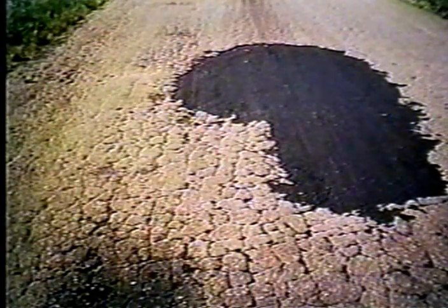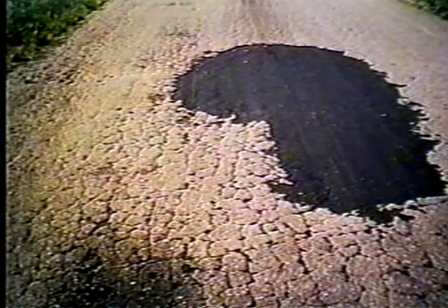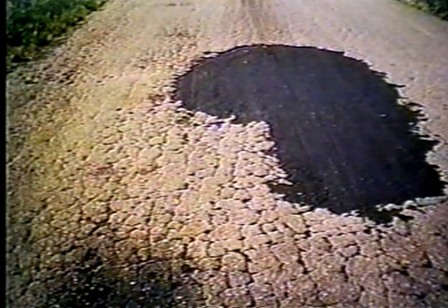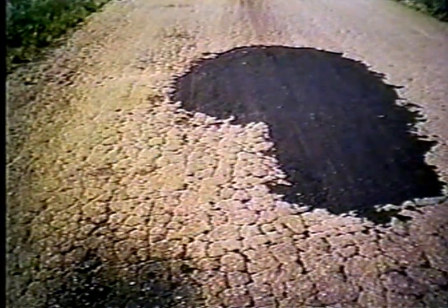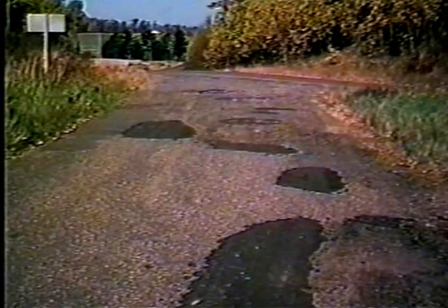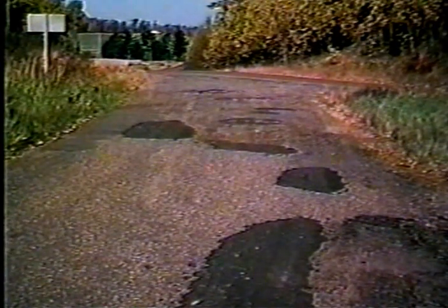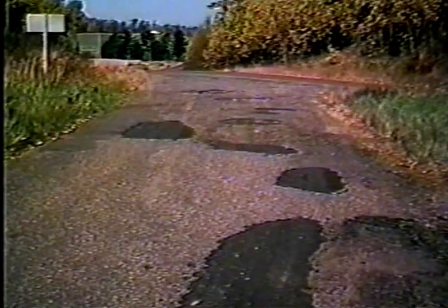Here's an extensive area of alligator cracking, and some patching has had to be done. Now, this is an indication that you can't fix this with a simple repair. You need to dig this out, rebuild it, restore the strength, and then proceed with other repair or rehabilitation. Further examples of areas with potholes and patches, indicators of almost total pavement failure and the need for total reconstruction. This completes the background information that we prepared for the pavement evaluation.